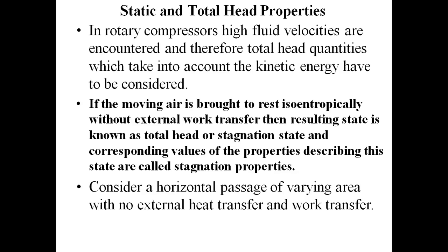If the moving air is brought to rest isentropically without external work transfer, then the resulting state is known as total head or stagnation state, and the corresponding values of the properties describing this state are called stagnation properties.